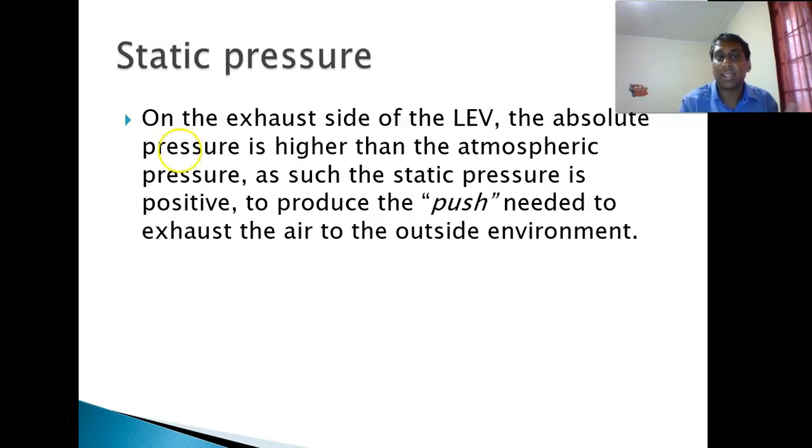I may be overdoing it on this explanation, but it would have just been: what is the instrument used to measure pressure? Students would have confused it, of course, with the anemometer, which is really airflow. Pressure is really the Pitot tube and the U-tube manometer anyway, right? Instruments measuring air velocity: hot wire anemometer, swinging vane anemometer, rotating vane anemometer.